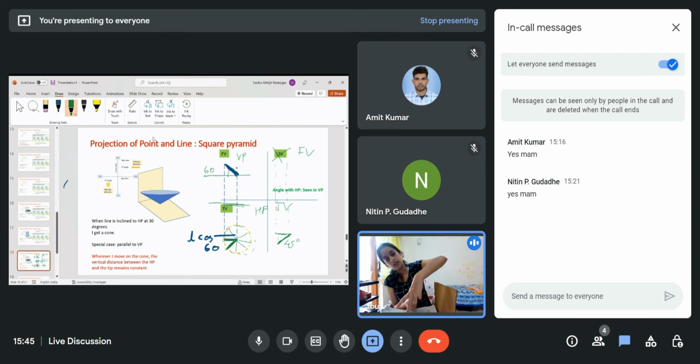So I'm projecting these two lines here, since this is at 45, I rotated this plane. Now I'm rotating this plane like this just to have it on our paper, because we cannot have 3D on our paper. So I had it like this, I rotated it like this, and now I'm projecting this length here.